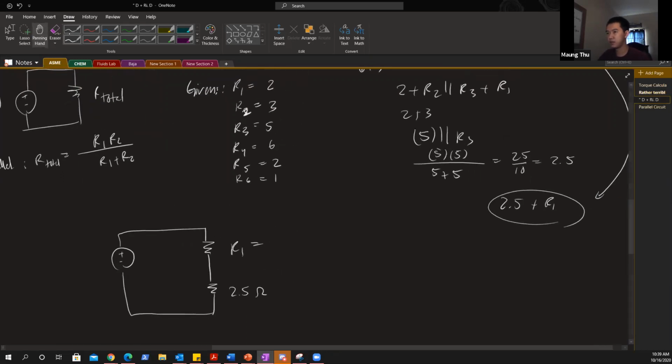So now it's so easy for you to draw and figure out voltages and currents, right? Because you should know, first of all, that current here is constant, right? Because it's in series. So current is constant. However, there's a voltage drop, V1, V2. Okay? And here is where the voltage divider equation comes in very handy.